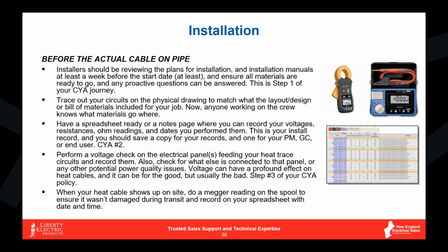When you put the cables on the pipe, you can also do resistance readings. What I would do is don't put your alligator clip across both bus wires at the same time. You always test each bus separately. That's a great practice to get into with heating cables, and if you're going to measure cables, that's the only proper way to do the measurement anyway. Don't try to clip both buses and do it at the same time. Individually check each bus wire.